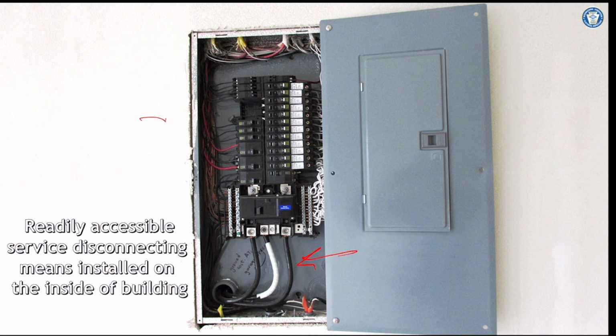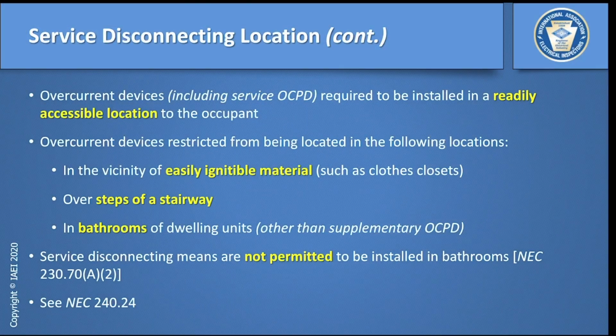So this is going to be service equipment. That's going to be service equipment. And you're going to have your grounding and bonding done correctly based upon the listing of the product. So if it's use only as service equipment, the grounding and bonding is going to be done for you. If it's suitable for use as service equipment, then you may have to make sure that you have the proper grounding and bonding inside.